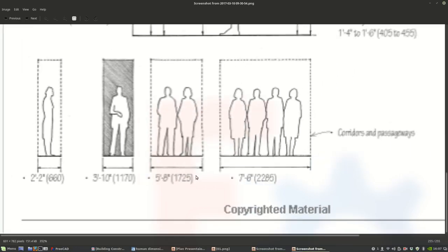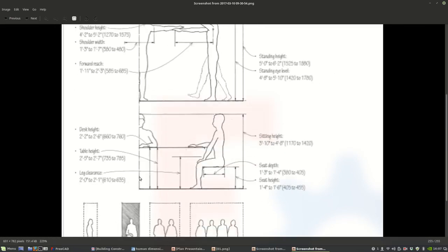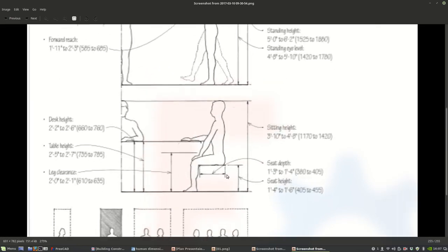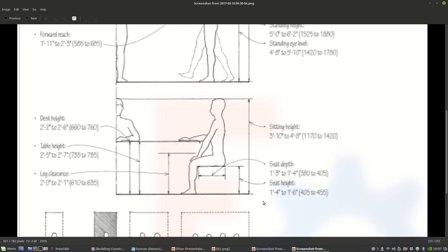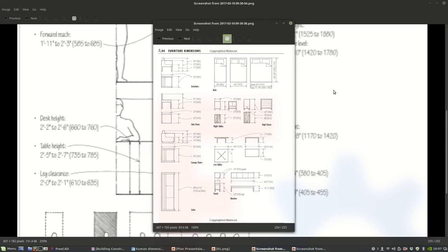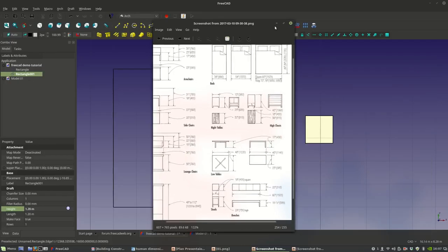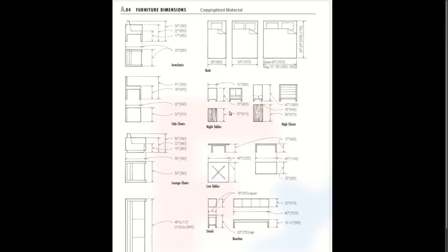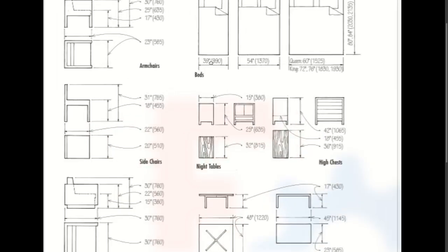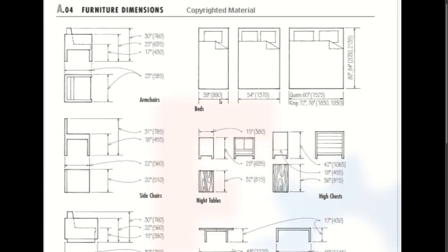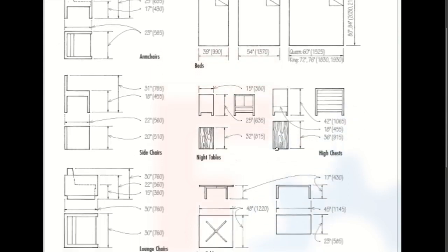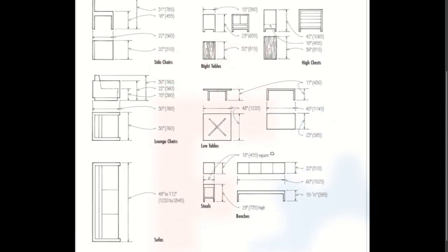and then what else? This just tells you what 2 people look like, and 3 people, and what sitting and seats look like. Here you will also have some of the seating position dimensions, 39 inches, and 80 to 84 inches for the height. So this gives you some general basic plan dimensions that you can work with that are standard already.